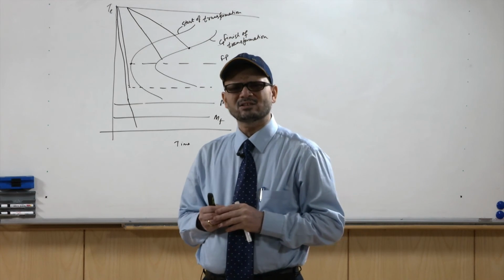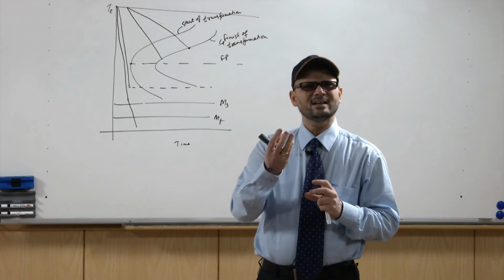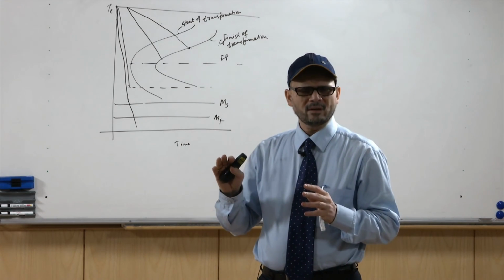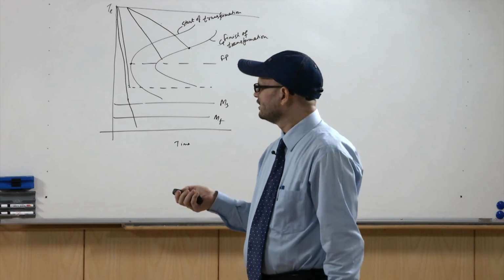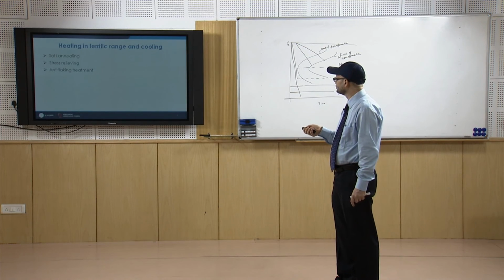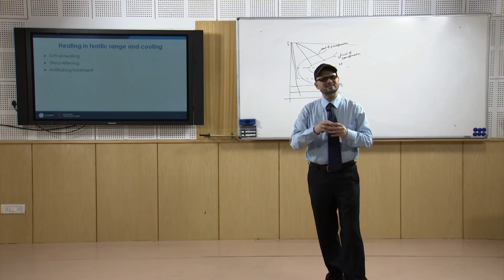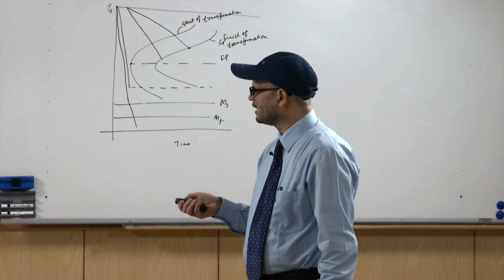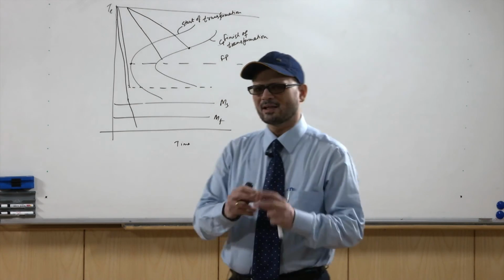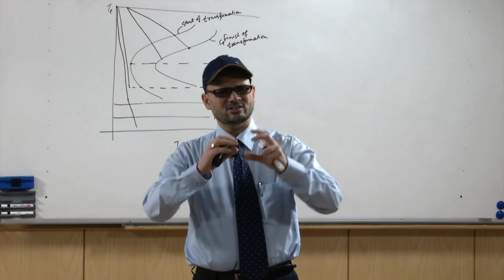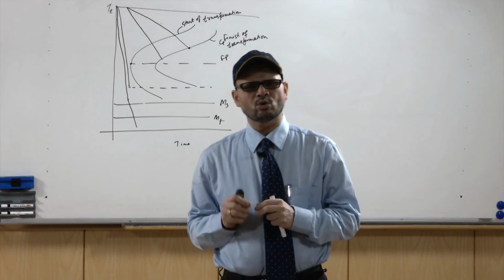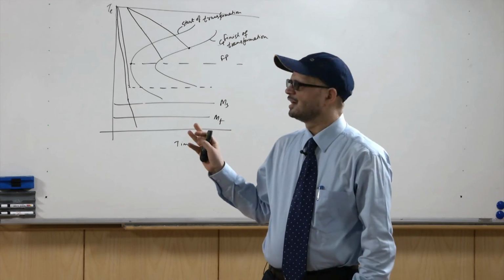For that, you heat and then maintain that temperature for long. Now, if your casting uses vacuum or some other treatment, this hydrogen can be removed, but otherwise you are heating and holding for a longer time, so that the hydrogen can go out and the casting becomes hydrogen free.